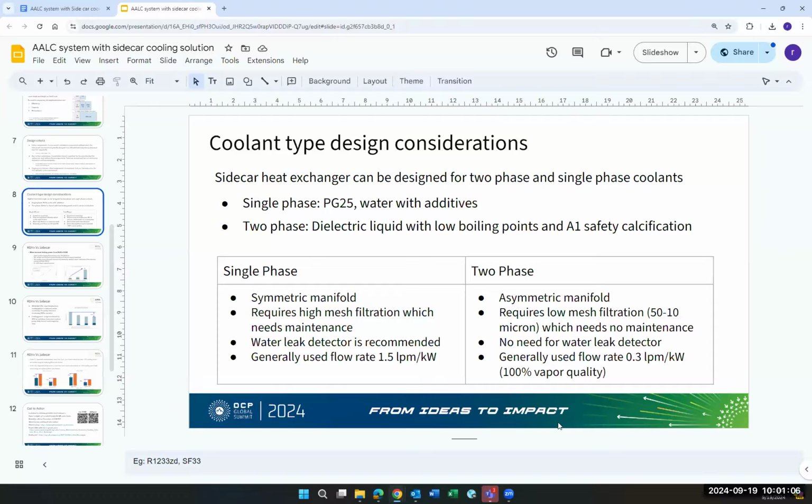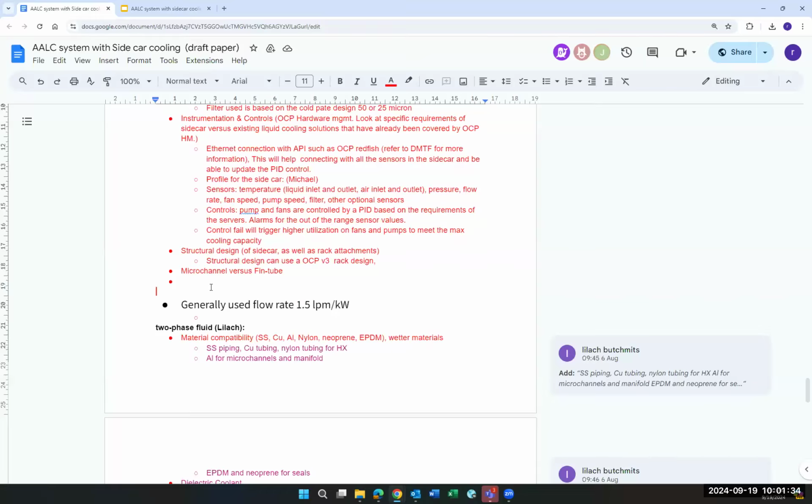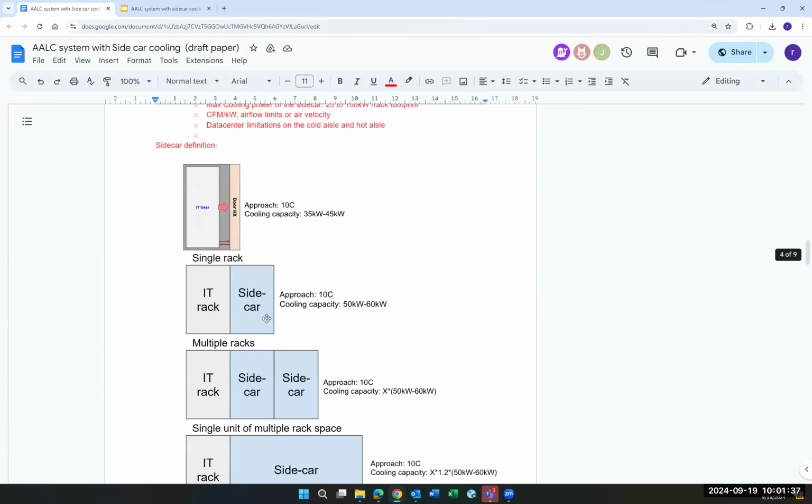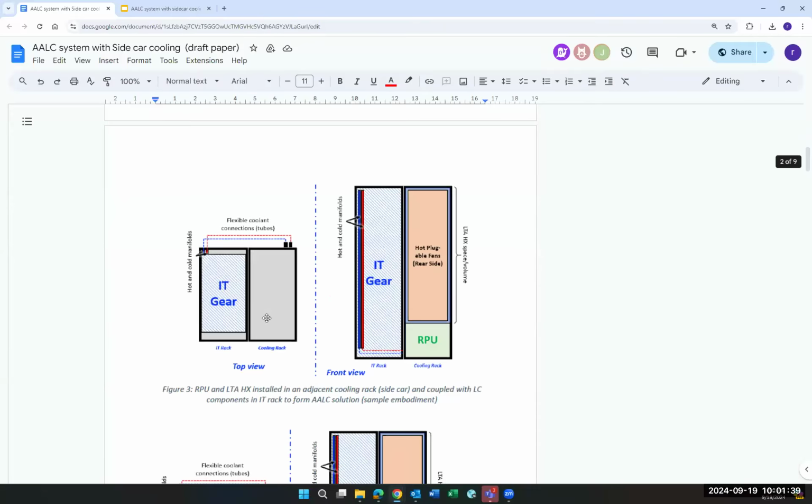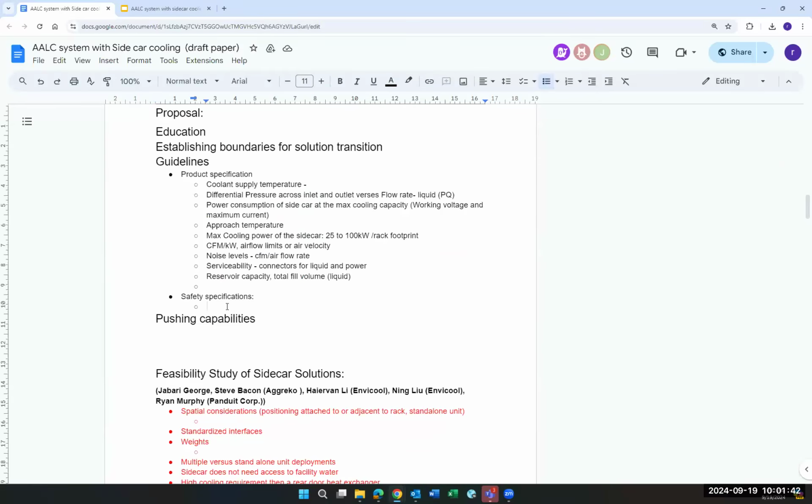You already have pressure sensors in place to identify the inlet and outlet pressures to make sure the saturation temperatures are in line with what you require, right? Yes, there are pressure and temperature sensors. Gotcha. Okay, we'll add that to the safety requirements in terms of leak detection and pressure maintenance, and so forth. We'll continue the topic.